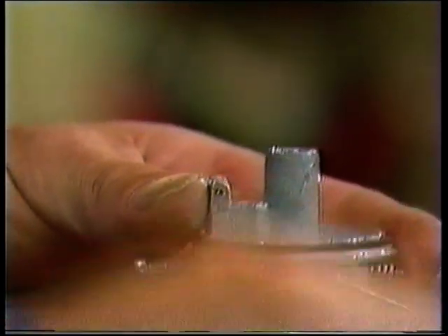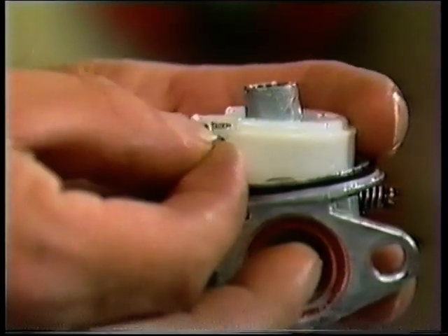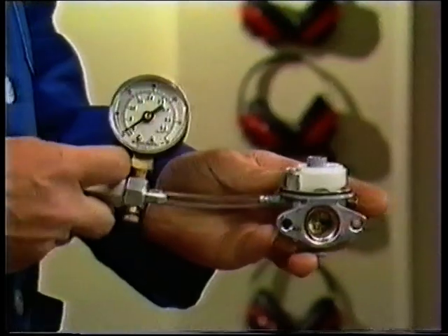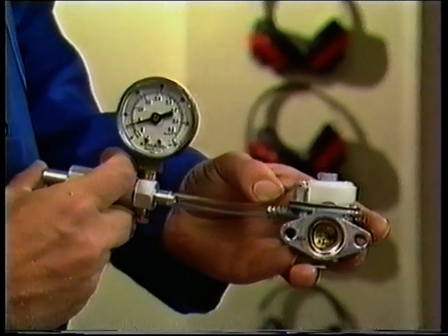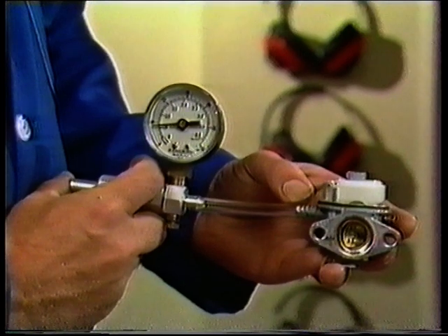Wet the needle and seat area with a small amount of gasoline and use a thumb pump to pressurize the inlet needle to at least 8 psi. The inlet needle should pop off and reseal at 2 psi or greater. If it doesn't, clean or replace both needle and seat and test again. If the needle seals and holds pressure at 2 psi or greater for at least 5 minutes, consider it acceptable. Otherwise, you'll need to do some additional testing.